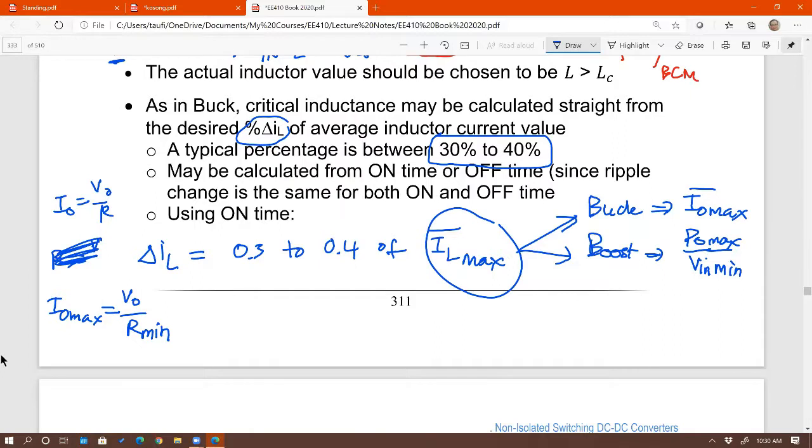Sorry, I didn't mean to cut you off. I'll just be quick. Our delta ILs are then based off of our Ls. You'll give us our L, and then we find delta IL off of that for both buck and boost converters. The delta IL, we typically find that given the inductance value, right? No, from a practical point of view, typically we pick L first, by assuming some delta IL. Is that what you meant?